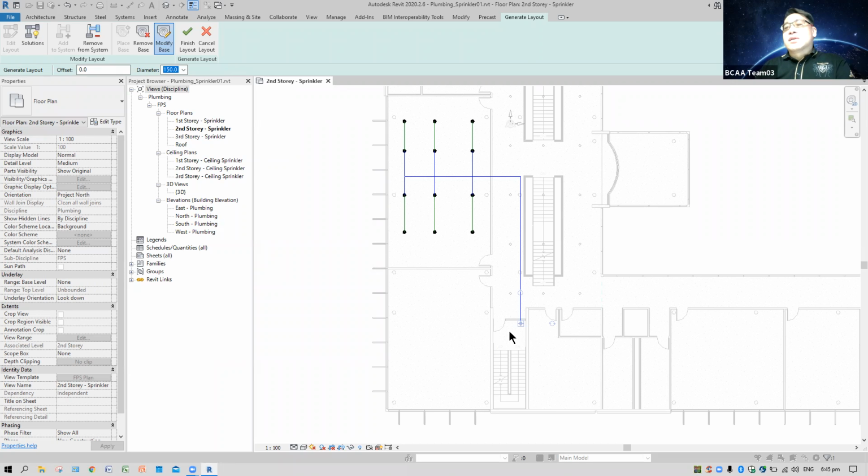Why? Because the smaller the pipe means what? The pressure is higher. Agree? When the pressure is higher, I need a more powerful pump. So at the end of the day, engineers have to take into consideration, let's say this is a 3-story building, what pressure is required when a pump is activated?